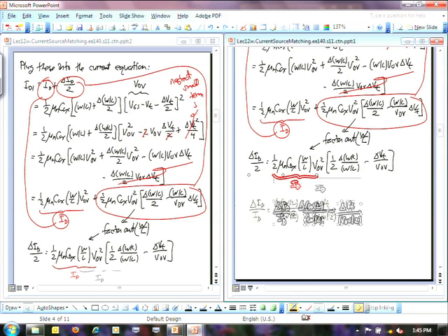It's the digital designers. It's the digital that people are pushing now, right? All the technologies are going for digital at this point. And with digital, the smaller transistors, et cetera, they're making the VDDs go smaller and smaller. Okay, so VDDs go smaller and smaller, and that means automatically your overdrive voltages have to get smaller.